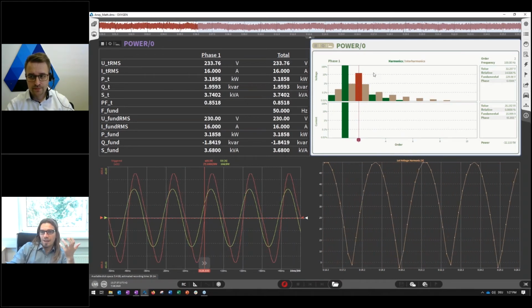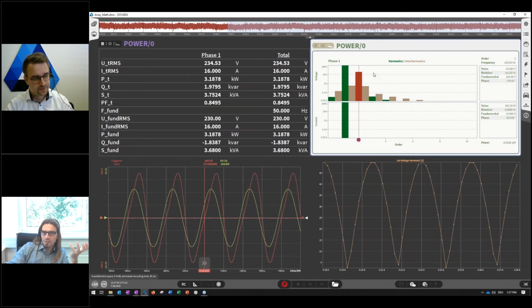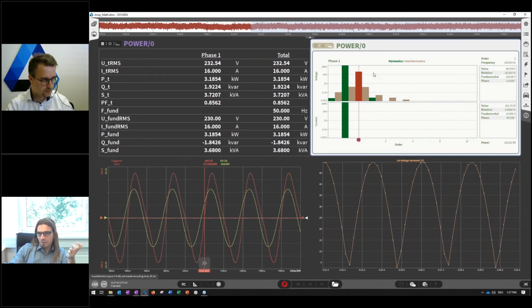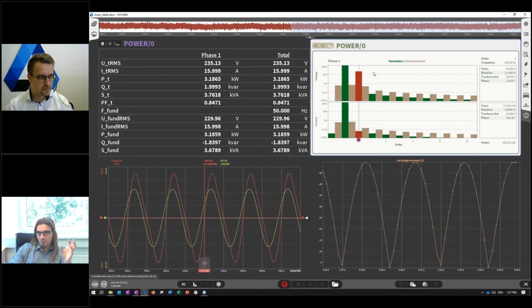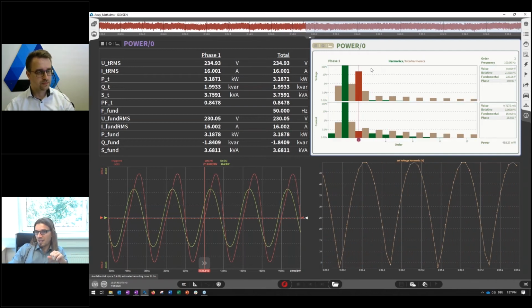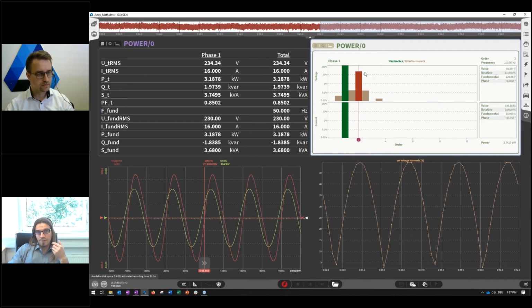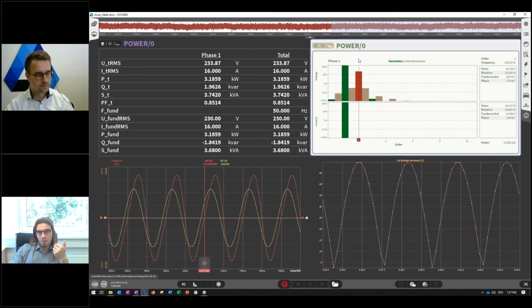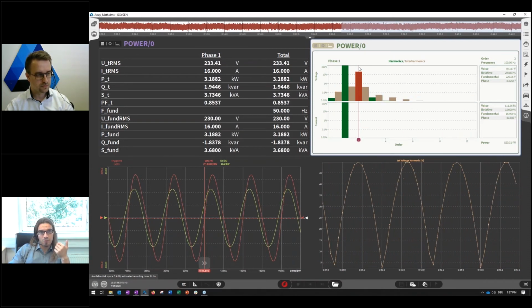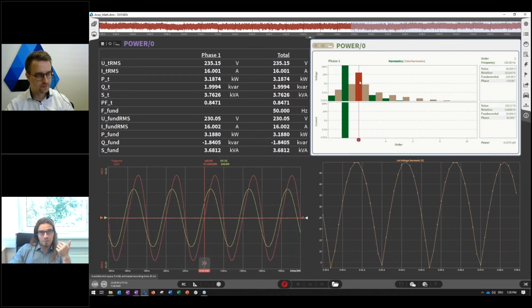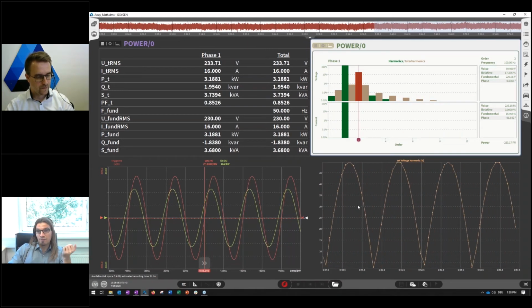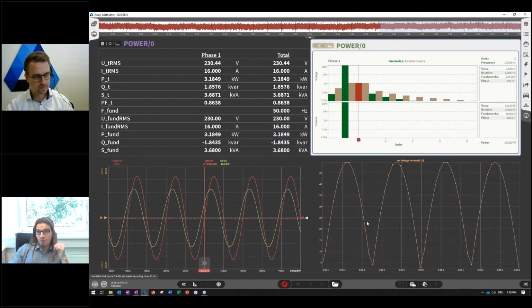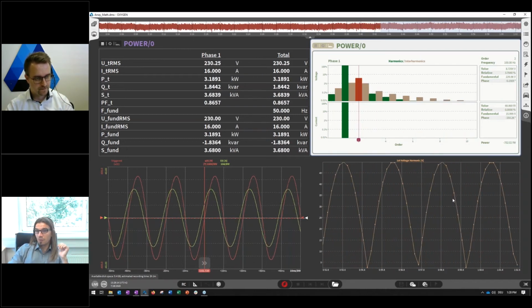And with this array math in the formula setup, I have the possibility to extract single values from certain cells of this array and to plot them in time domain, for example. I prepared a small example here. So you see the second order of my voltage channel here, which is constantly changing. And now you can extract this harmonic order, the second harmonic order, for example, in time domain, and visualize the time-dependent trend of the harmonic here, for example, in a recorder.